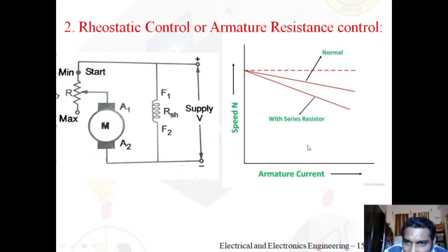As the load increases, the gap increases. At small loads the gap is small. As the load increases to rated values, the difference increases. But still, the speed regulation of a DC shunt motor from no load to full load is good, less than 1 or 2%. The efficiency is more.